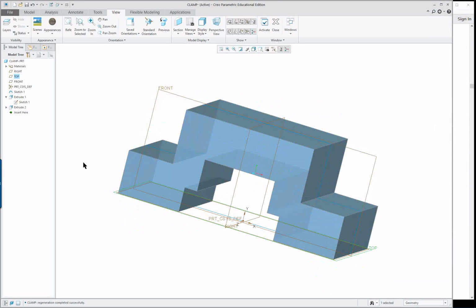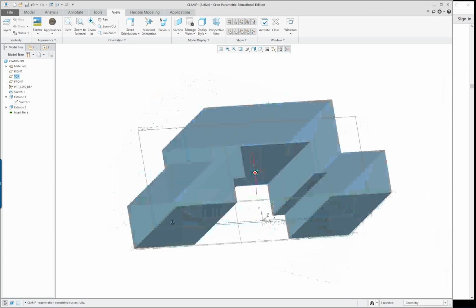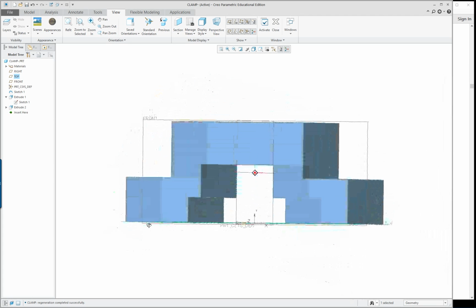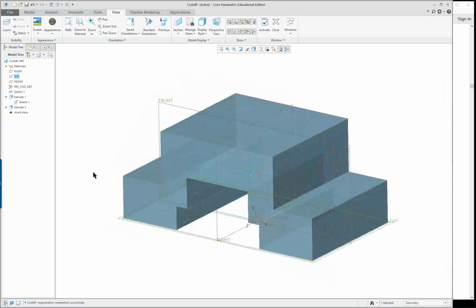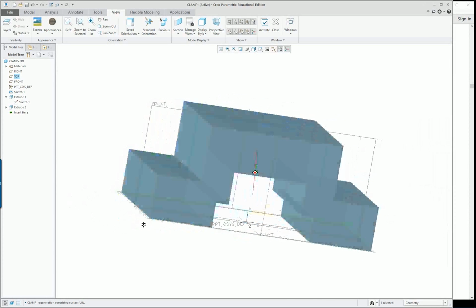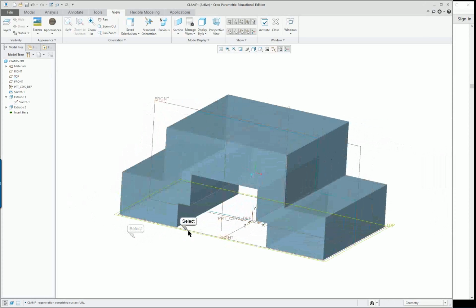I'm going to sketch on the datum plane because it's one of the first features way up here, and it's least apt to have any changes made to it, obviously, because it's the base or the original datum plane. But these other surfaces, edges and that, they could change during the modeling process. So I'm going to actually select that as my sketch plane for my cut.